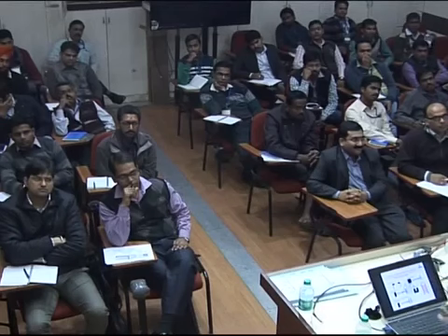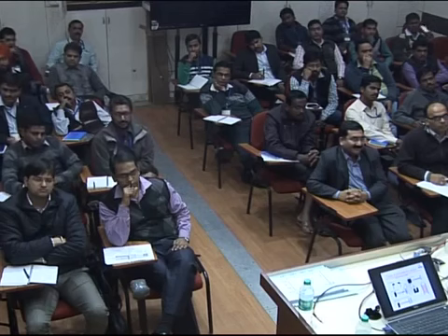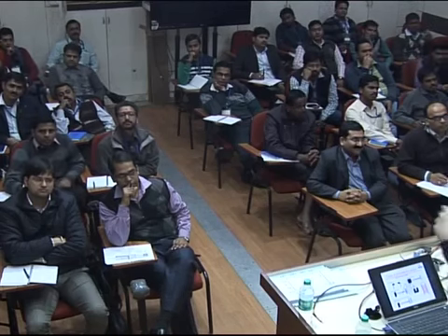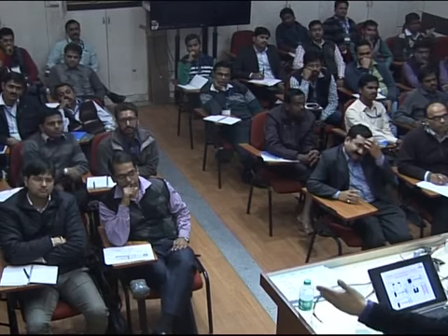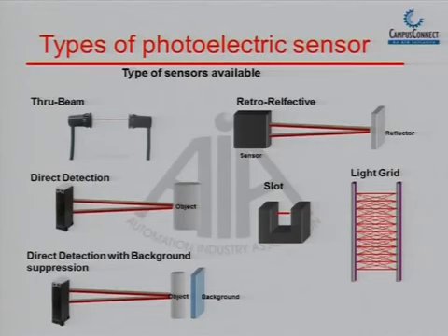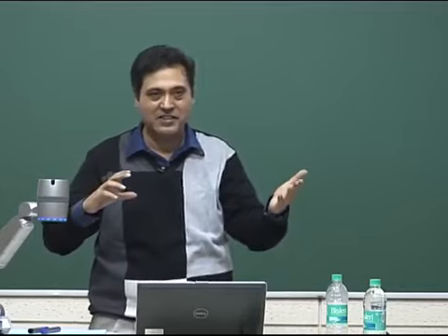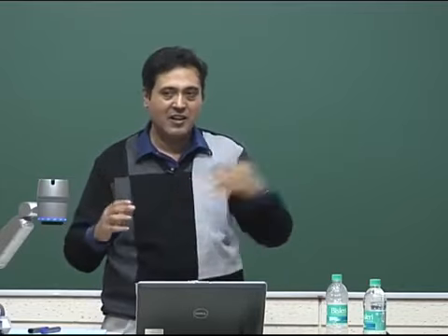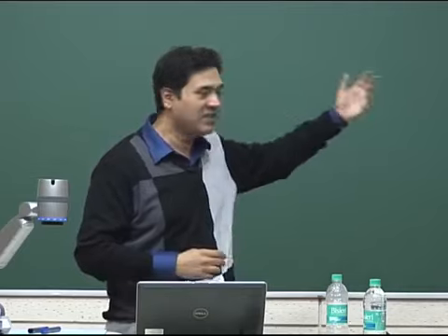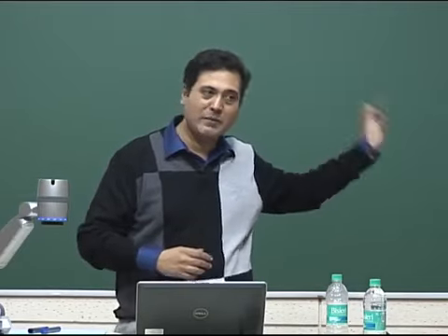No sir, these are the second category of sensor, that is a retroreflective sensor. In that we require a reflector in front of it. This is my sensor, this is a reflector. The light from the sensor goes to the reflector and gets reflected back. Now if I don't have a reflector, and in the middle I bring something like a mirror or a very shiny surface that can reflect back the light, will the sensor still get an output? Will it be able to sense it or not?